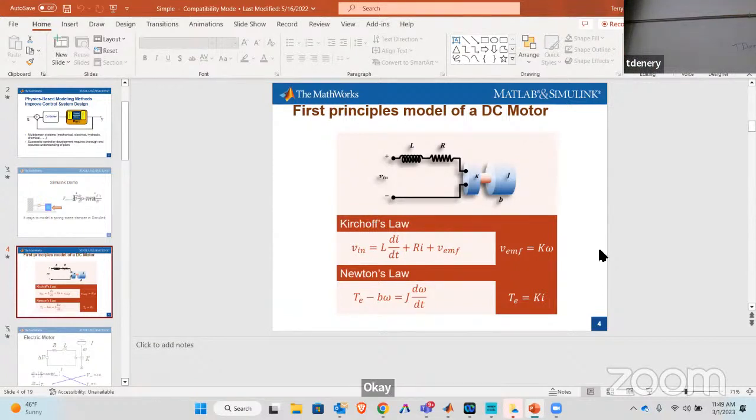I've been looking at this for 20 years, so it all looks obvious to me. But there's essentially Kirchhoff, and the key origins of how you need to consider a DC motor. Kirchhoff's really great for circuits, and we've got a general description of the circuit right here. The DC motors are represented by their inductance and their resistance, but they have this magic thing: if I put current through the wires, based on how those windings are aligned with a permanent magnet, they generate torque, and we quantify that with the torque constant.